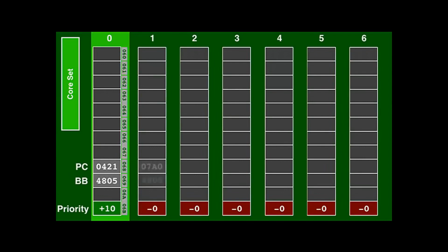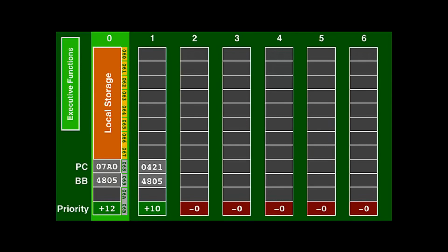When a new job gets created with a higher priority, the yield operation will exchange the 12 words so that new job is job 0. Negating the priority will put a job to sleep, so yield won't switch to it again. Negating it again will wake it up. The first 8 words in the job entry can be used for local storage for the job. Since it's always job 0 that is running, these words are always conveniently located at the same addresses in memory.